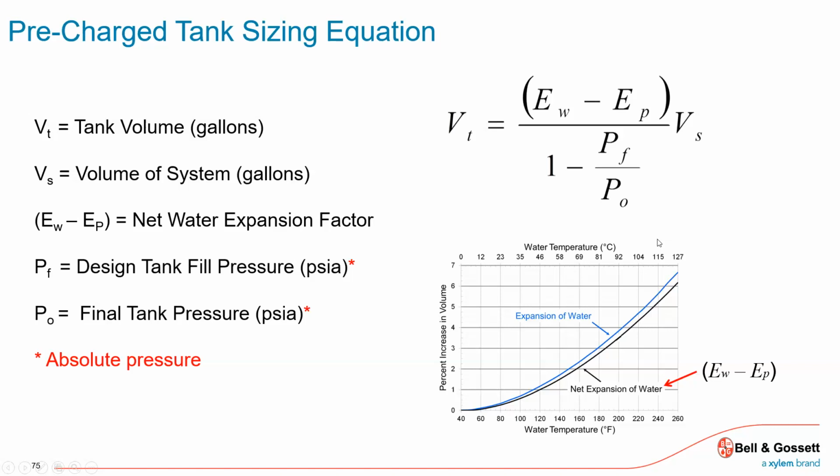And then what's my fill pressure and what's my relief valve pressure? So what's my starting point? Because that's a certain amount of pressure sitting on that relief valve. And then what is the relief valve setting? So there's that range I've got to play with. So I've got to do two things. I've got to absorb the volume of water. I've got to have a place for it to go. And in doing so, I've got to make sure that my pressure increase doesn't blow the relief valve, because then it defeats the purpose of why I specified and put in an expansion tank.